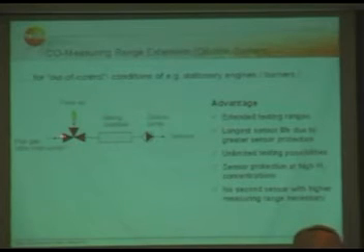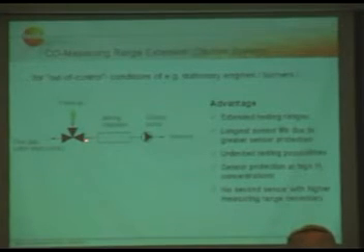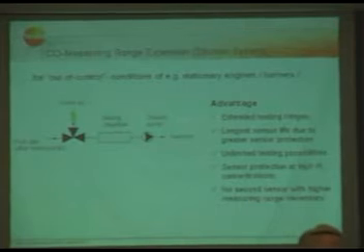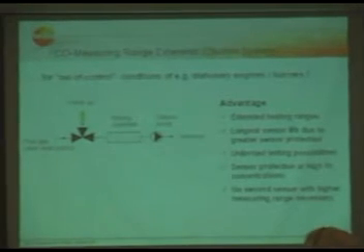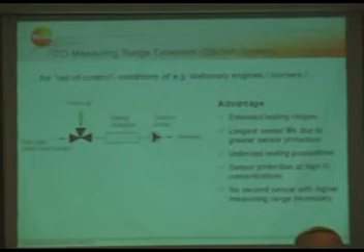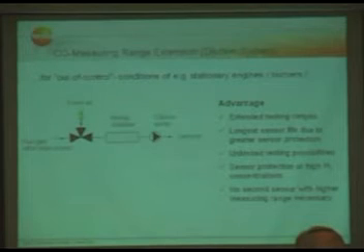Basically, the flue gas comes to the analyzer through the hose and the sampling probe, and all we do is mix the flue gas with fresh air within a mixing chamber, and then the mixed fresh air and flue gas gets to the sensors. Depending on the dilution factor, we can dilute from 2 times up to 40 times. The dilution factor is freely selectable. A valve will put fresh air and flue gas together according to the dilution factor.